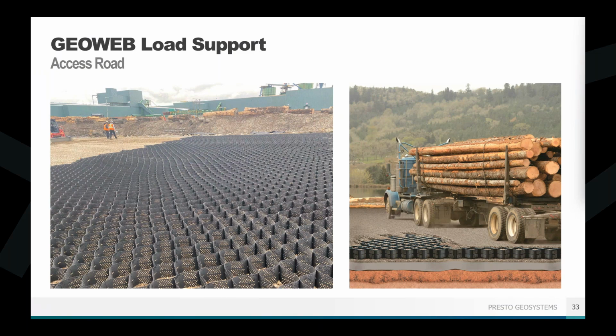In this case, it was a 6-inch deep GEOWEB panel that was installed above a single layer of a geotextile to confine that crushed aggregate infill and provide that strong reinforcement layer to support frequent and heavy vehicle loads. We also limited the fines within the GEOWEB material to help promote that drainage. So in this case, we said the fines content, so your silts and your clays, had to be less than 10%.